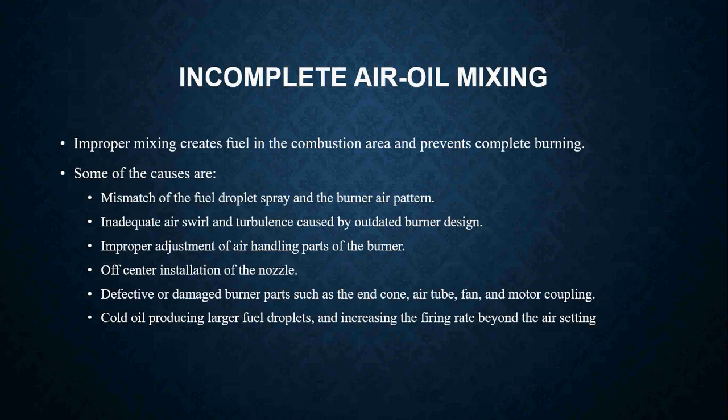So if you have an older burner attached to a newer piece of equipment, that can create air turbulence and inadequate swirls, so your air and fuel mixture is not going to be correct. Improper adjustment of the air handling parts of the burner, like your primary and secondary air bands, simply not adjusted to where they need to be.